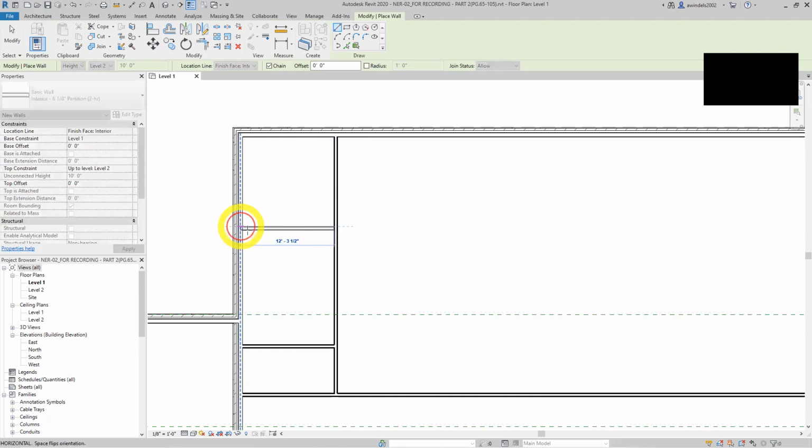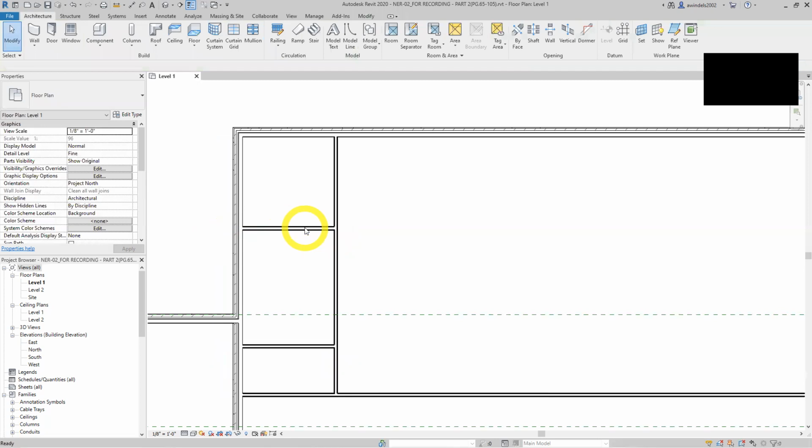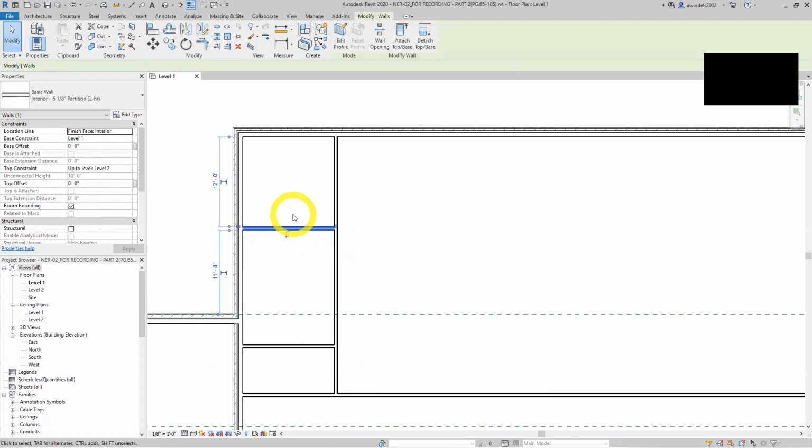Let's just try this. So we don't know the dimension. This is kind of a trick. They don't have all the dimensions. This one, they have this dimension from here to here is 12 feet. It wants to keep that. So I drug it down there. I'm just kind of tricking out the temporary dimensions to make them do what I want. Now it's 7. Let's try that now.